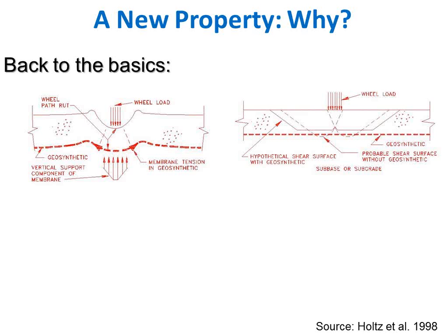If we have a reinforcement, without a reinforcement, if we have a failure surface, a bearing capacity, they treat this as a bearing capacity problem. So if we have a bearing capacity problem, it's really a shear failure problem. So if the failure surface wants to go in a given direction, and then we put a reinforcement and we modify, then we modify the failure surface essentially by forcing the failure surface to go in a different direction, we're increasing the factor of safety. Now, while these are two, I would say, valid theories, they are valid perhaps for unpaved roads.